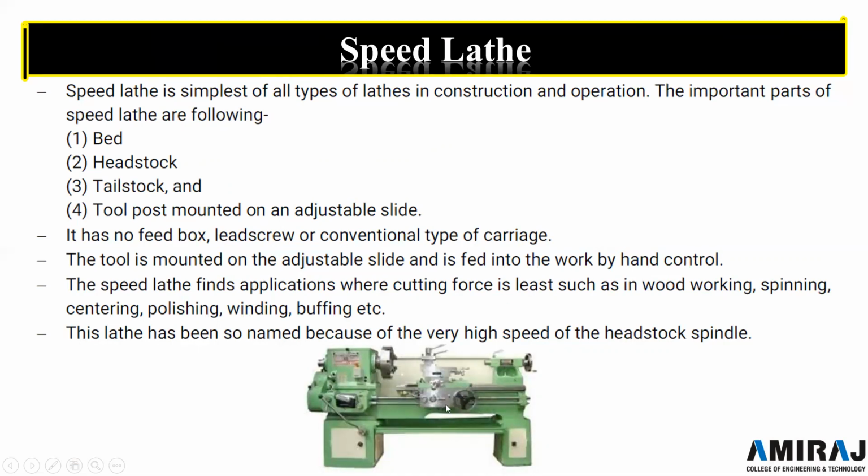In this, it is shown that there is one simple type of mechanism, that is the slider type. There is no lead screw arrangement. It can only slide over here. The tool is mounted on an adjustable slide, with a lock and nut type arrangement. By rotating this handle, we can slide this complete post and move it to a particular position.